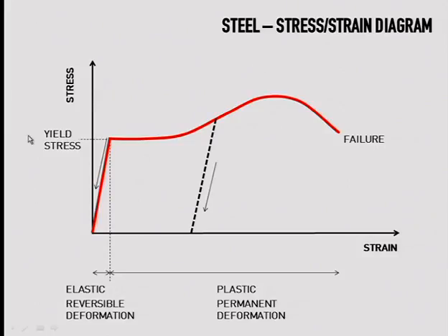You recognize this because there is a linear proportion in the development of this elastic phase, and then it changes suddenly, and there is not a linear proportion in the ratio between stress and deformation. But that's very important. So both in tension and compression, that would be the behavior, and it is a ductile behavior because of this plastic phase we see here.